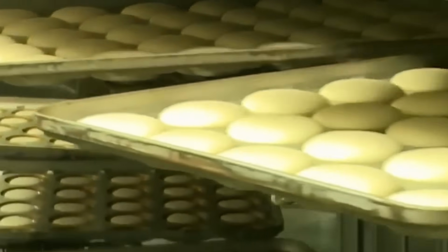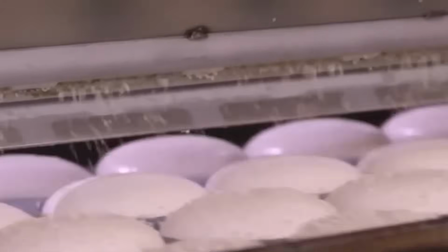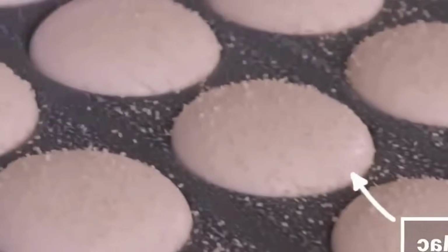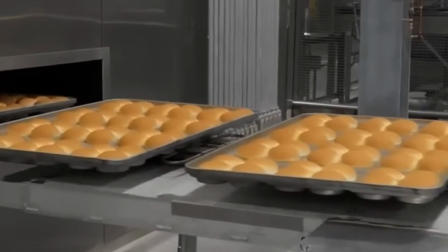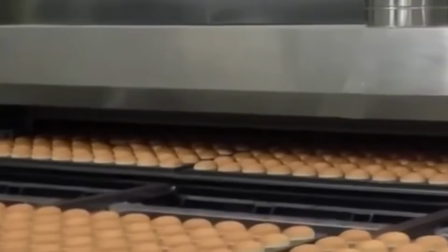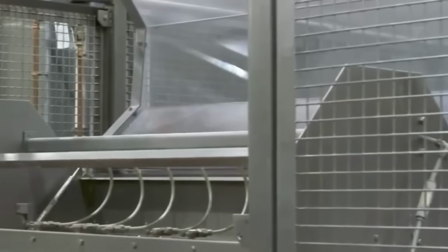Grill platen pressure is balanced to avoid sear marks that penetrate too deeply. Contact time is calibrated to match patty water content and surface heat conductivity. Belt tension is maintained through spring-loaded rollers at both ends of the grill. Drip pan contents are filtered and cooled before disposal.